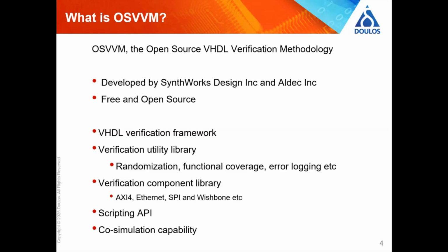So it can be much more appealing for VHDL engineers to say, well, can we do this in VHDL? The answer is, in native VHDL, it's actually pretty difficult. There's no native support for coverage in VHDL. It doesn't have a way of measuring whether I've actually given the value 100 to this particular signal at any particular point in the simulation. And also, its random stimulus generation is fairly primitive. We've got the ability to create random numbers, but basically we've got uniform, and that's it. There's nothing much else there in VHDL.